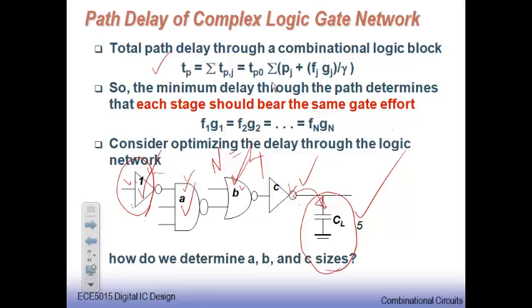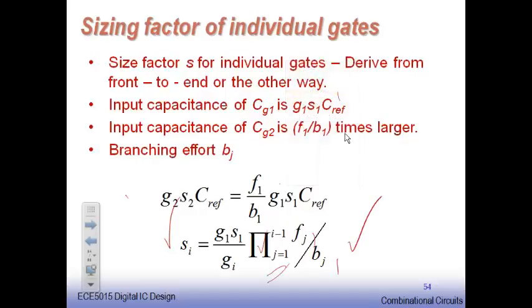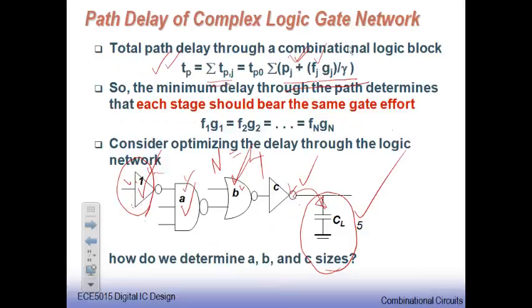Now the time delay, the TP, is going to be the sum of individual delays. I have individual expressions, and I sum everything. That is what gives me TP. And individually, when I look, I have for each the delay factor, for each the fan out load factor, for each the logical effort, and gamma I assume 1.